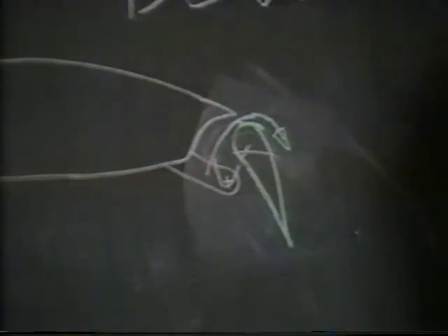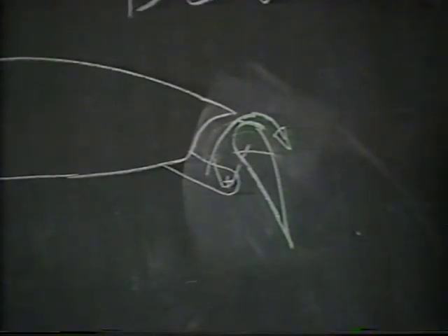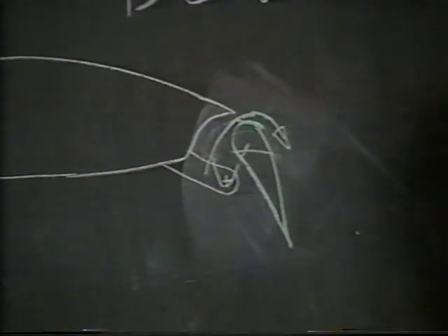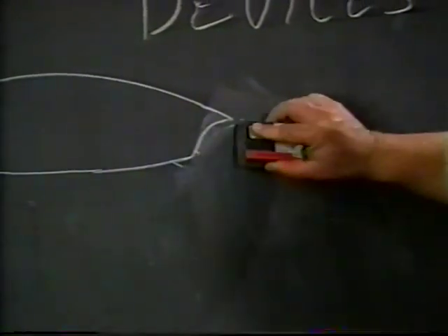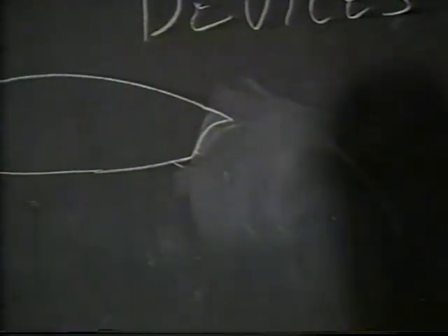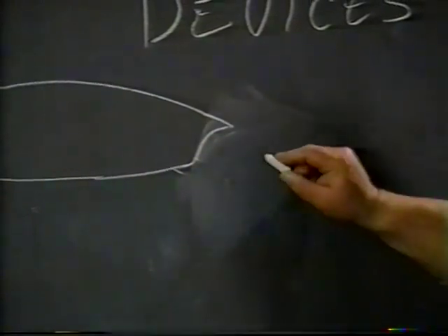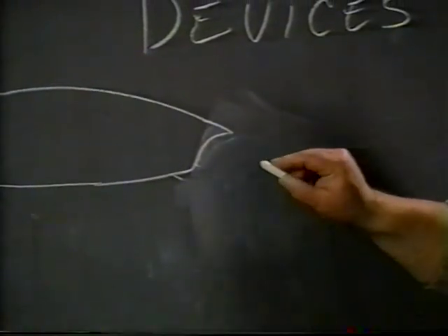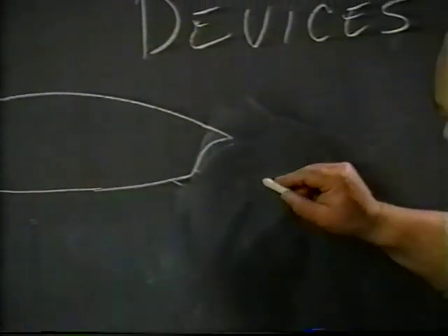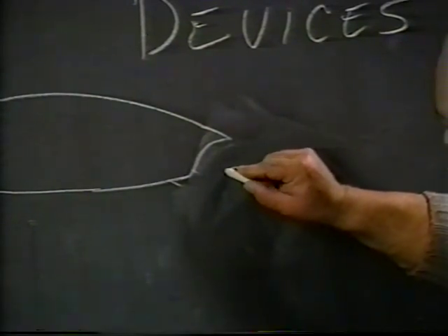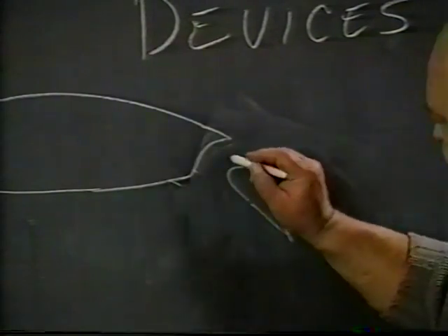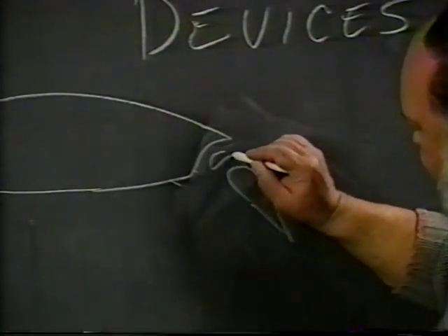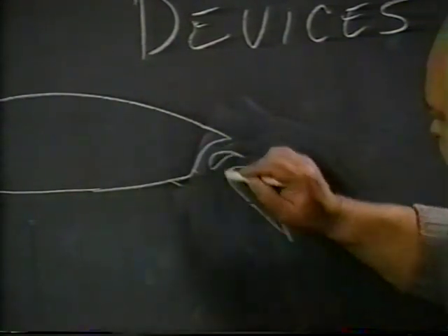The one that we have that would be better than this would be a double slotted flap. And really, what that comes out to be is something very, very similar to the single slotted flap, except that the flap itself, and I'm just going to draw this flap now in the down position, has two slots essentially in it. First, you got the flap section itself, and then a little auxiliary airfoil built into it.